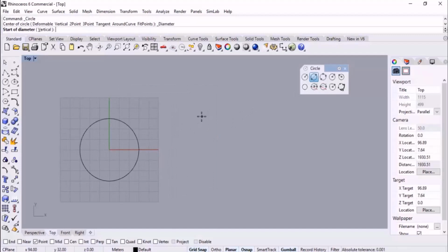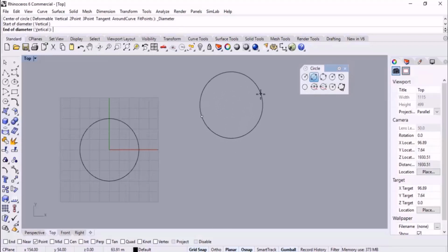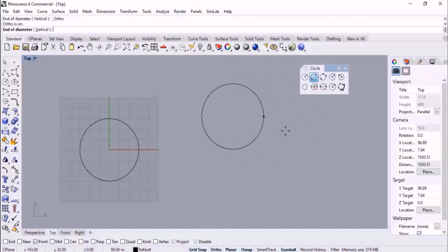For example, here in the scene I want to sketch this. As you can see, the size of the circle is based on the diameter, not the radius. And when you are clicking, note the points like @ or the less than symbol for specifying the angle or the length. All of these are applicable to the circles too. I press F8 and then I want to specify the value of the diameter, 30 for example, or 25. Then as you can see, I can specify the direction or end of the diameter.